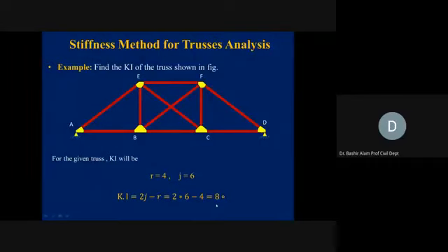Now, to illustrate this with the help of sketches, we have this frame. This is a truss, and we need to find the kinematic indeterminacy of the truss. If we look at A, B, C, D, E, and F, these are the 6 joints. So J is equal to 6 is recorded here. And reactions: at A we have a hinge support, so 2 reactions are coming from here.